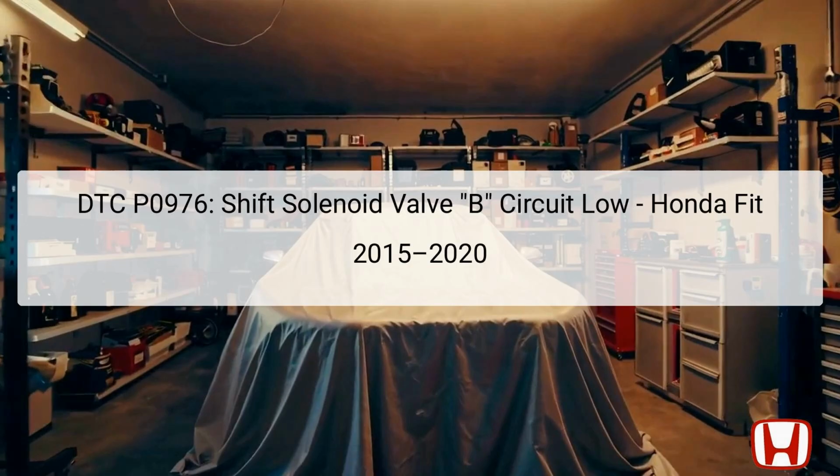The solenoid valve B directly connects to the powertrain control module, PCM, located under the dashboard, and is integral to the transmission's operation. It operates based on electrical signals routed through the vehicle's wiring harness. Therefore, troubleshooting this DTC focuses heavily on electrical diagnostics rather than mechanical issues.